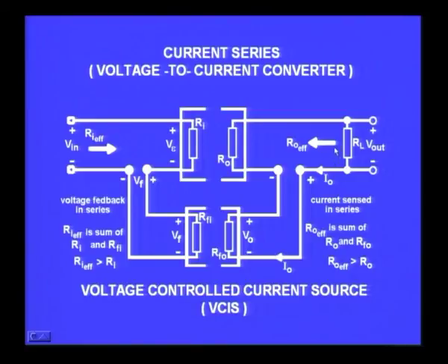So what is the effect of that? Because the output impedance is increasing, this becomes a current source. It is not a voltage source, because only for a current source the output impedance is very large. Usually for an ideal current source it is infinity. And at the input the resistance is increasing, that means the input will have to be a voltage. So you have a voltage at the input with a large input resistance for the effective amplifier, and you have a large output impedance corresponding to a current drive at the output, and therefore it becomes a voltage to current converter. Input voltage will be converted into a current by this feedback arrangement, or it also can be called a voltage controlled current source, VCCS.